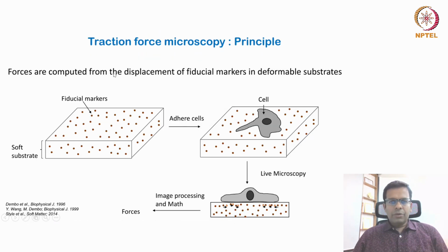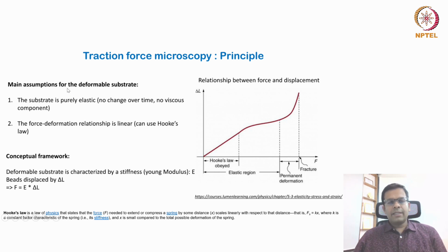Before going into it, let me explain the main assumption for the deformable substrates here. The substrate is purely elastic and it will not change over time, there is no viscous component present, and the force-deformation relationship is linear, so we can use Hooke's law. This is the conceptual framework. The deformable substrate is characterized by stiffness or Young's modulus E, with displacement delta L. So F is equal to E multiplied by delta L, where delta L is the displacement.